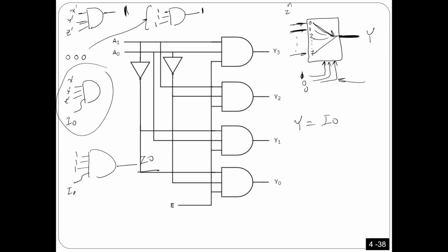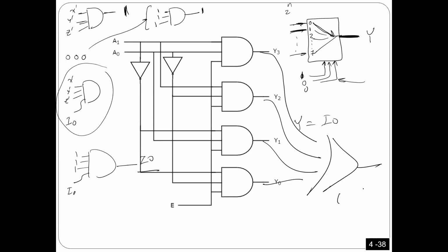I'm gonna use the same design, but add one more input here, and because I have only one output, I'm gonna take all these values together and OR them, and this is the output. But keep in mind, only one of them is on, all the others are off. For example, if the input is number 3, this one is producing input number 3, and all the others are 0. All of them are 0 except the one you selected with the input. Any question?